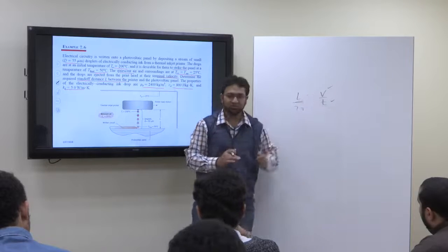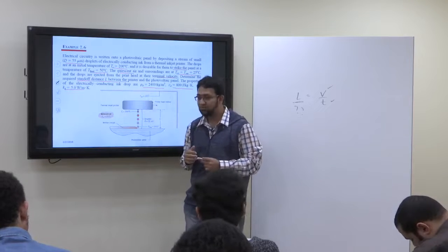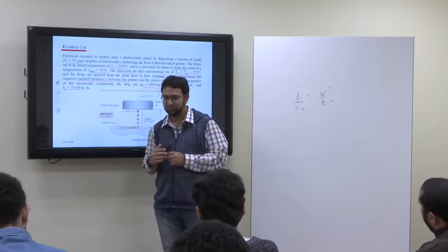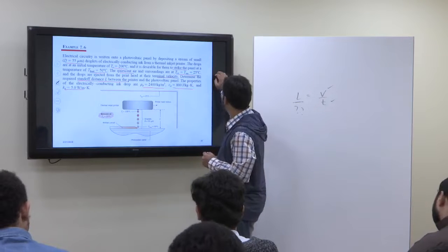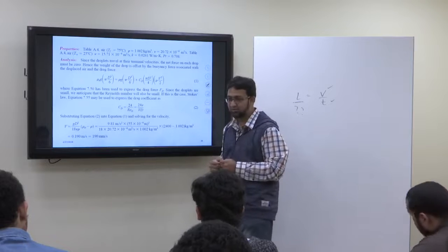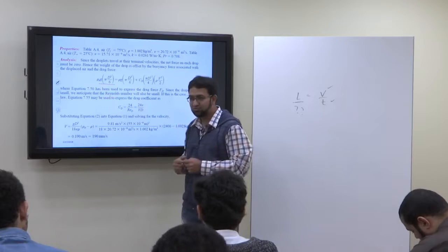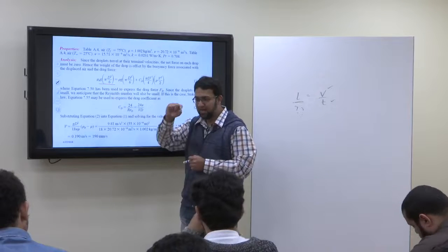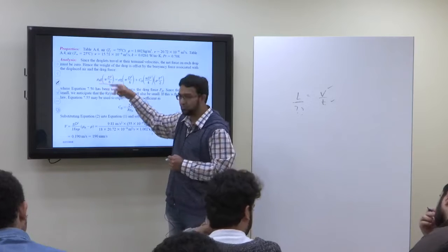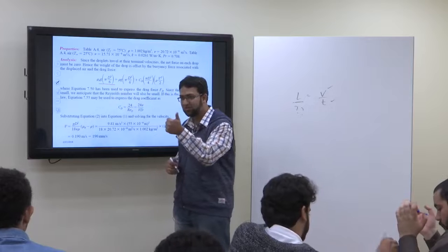So let's talk about the velocity. It will be the terminal velocity. But is it given? It's not given. However, we can find it, and this is actually what we did last time, by doing the force balance. We have the force of gravity acting on the droplet, F equals ma, but mass converted in terms of density and volume. This force is equal to two forces: force of buoyancy and force of drag.